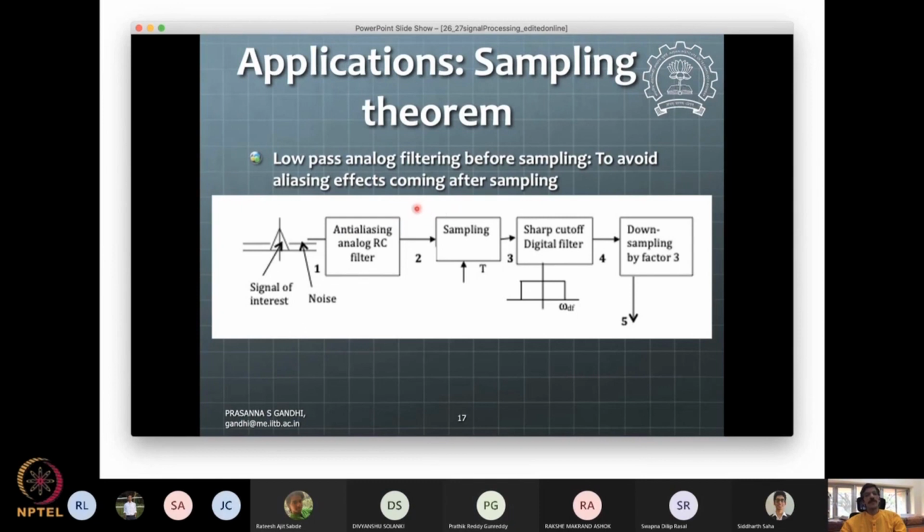The original signal will be there, and then with the anti-aliasing RC filter, the signal beyond this point is tapered down to some very small value. This 20 dB sloping cutoff will not leave it constant going over like that. As the frequency increases, this filter will lessen, taper off or chop off the higher frequency signals.